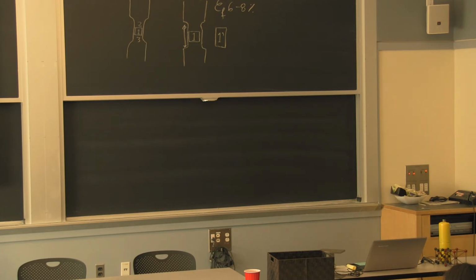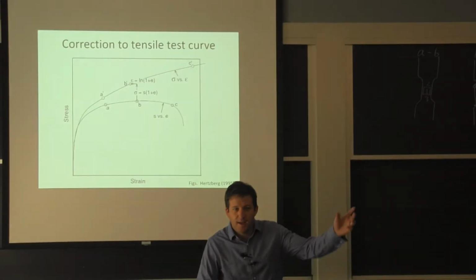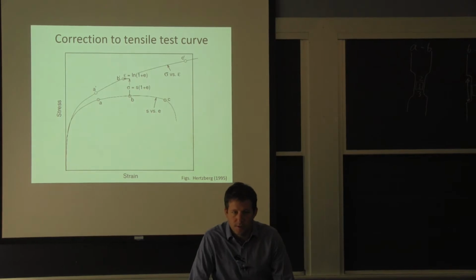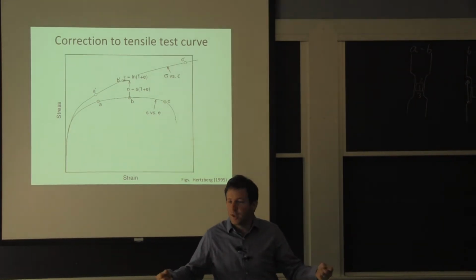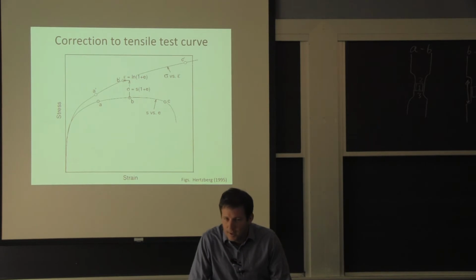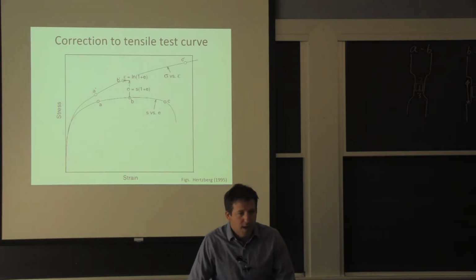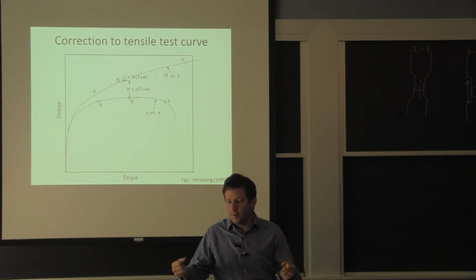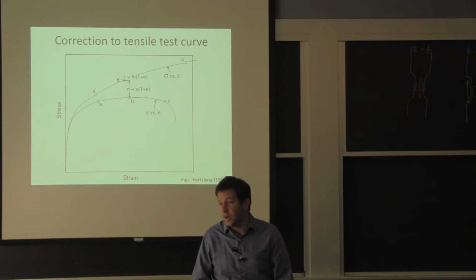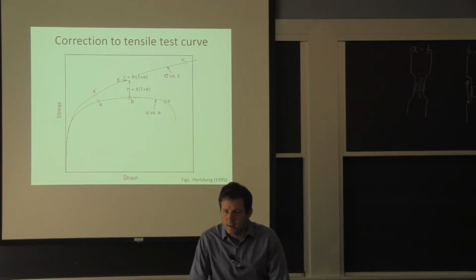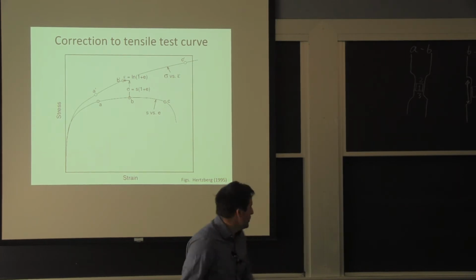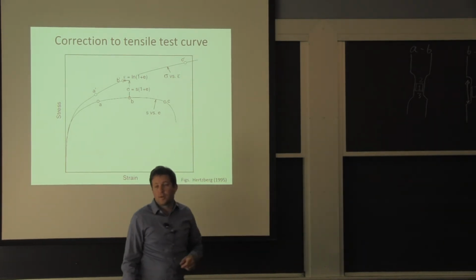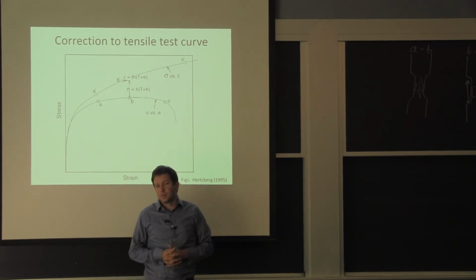So if I take a piece of copper for, say, electrical lines, it's very high purity, and the only way they want to use it and hang it from one transmission tower to the other is in a very, very stretched condition. It's work hardened. It's so work hardened that when I pull on it, it doesn't really want to harden anymore. It's beat up to death. And therefore, it will be necking very early on, so it will show like it has no ductility whatsoever. But it's pretty much at C prime up there already when you put it in service.